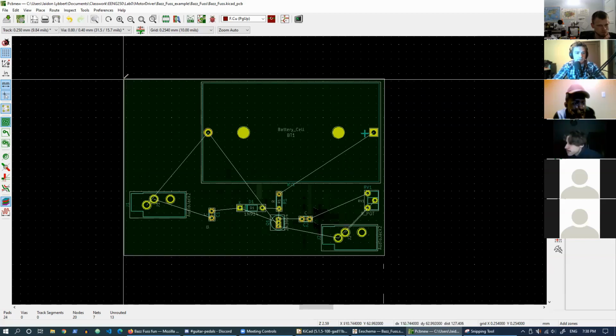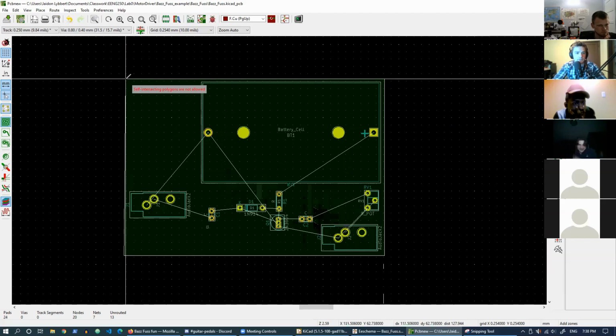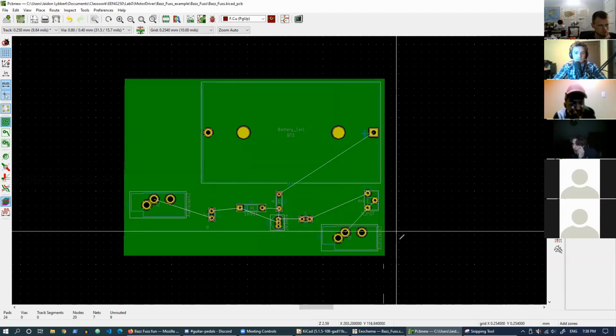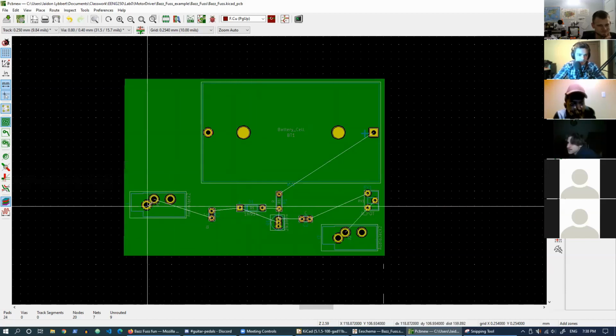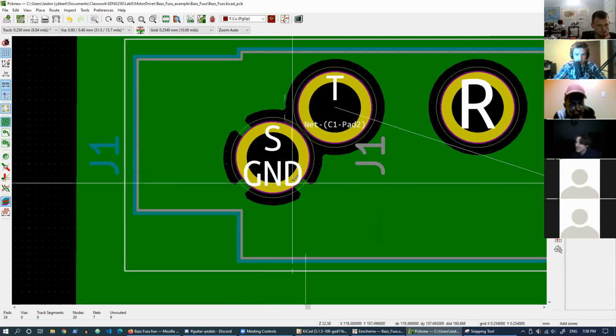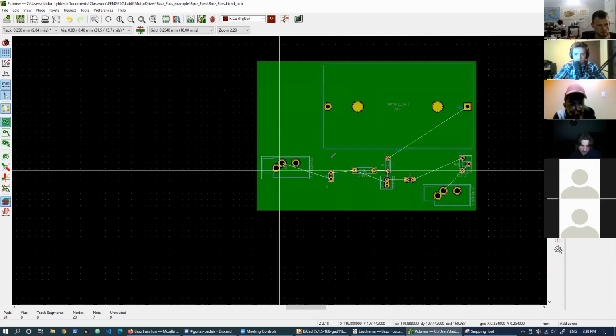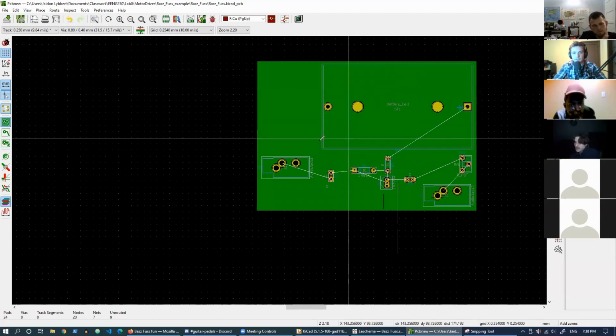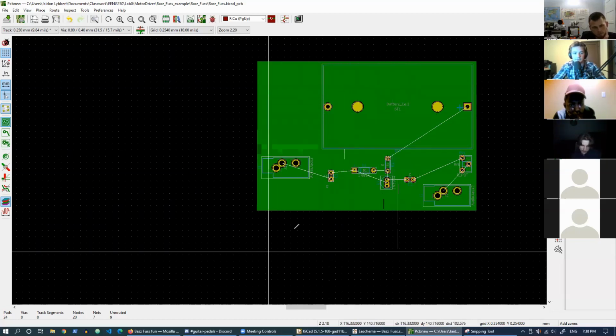And then just close it here, or maybe I just right click and hit close. Yeah, so now you can see right here, this is ground and there's copper attached to this pad. And all those white lines that were attaching the grounds are now gone because they're attached by the ground plane.